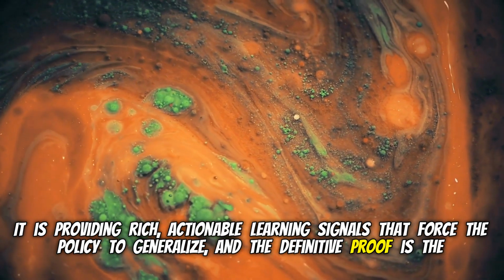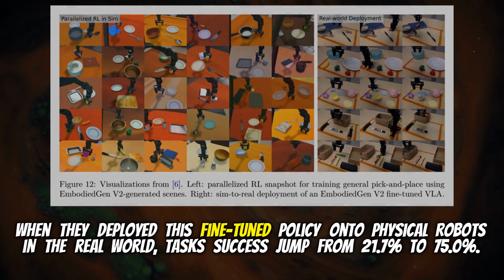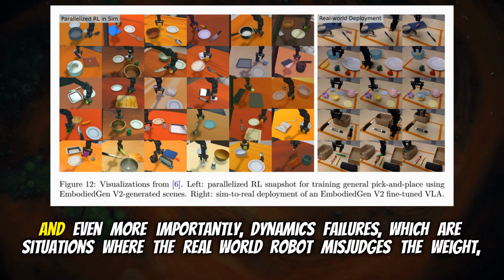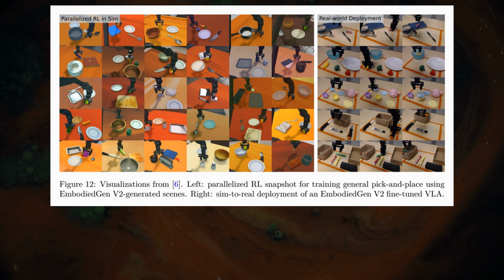And the definitive proof is the sim-to-real transfer. The real-world test. Yeah. When they deployed this fine-tuned policy onto physical robots in the real world, task success jumped from 21.7% to 75.0%. That is just incredible. And even more importantly, dynamics failures, which are situations where the real-world robot misjudges the weight, friction, or physical behavior of an object, those plummeted from 66.7% down to 18.3%.